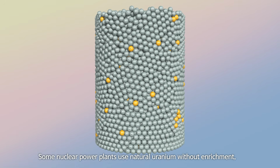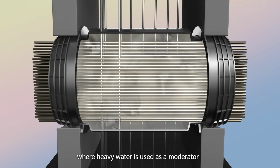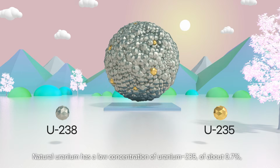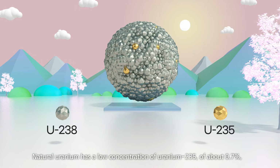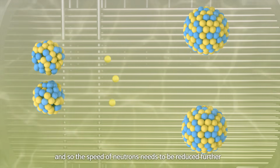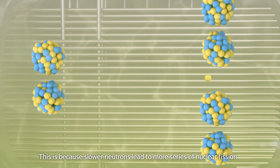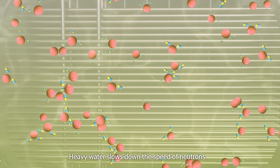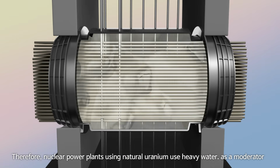Some nuclear power plants use natural uranium without enrichment, where heavy water is used as a moderator. Natural uranium has a low concentration of uranium-235 of about 0.7%, and so the speed of neutrons needs to be reduced further. This is because slower neutrons lead to more series of nuclear fission. Heavy water slows down the speed of neutrons more than light water simply because it is heavier. Therefore, nuclear power plants using natural uranium use heavy water as a moderator.